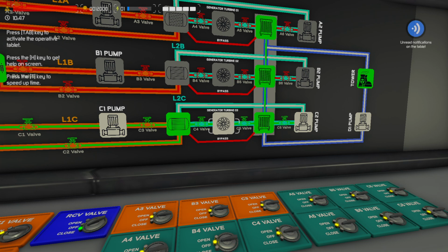So the steam hits the blade and causes it to move because of friction. But then there are several sets of blades stacked next to each other, and each blade it hits, it's imparting more force and using up that energy.